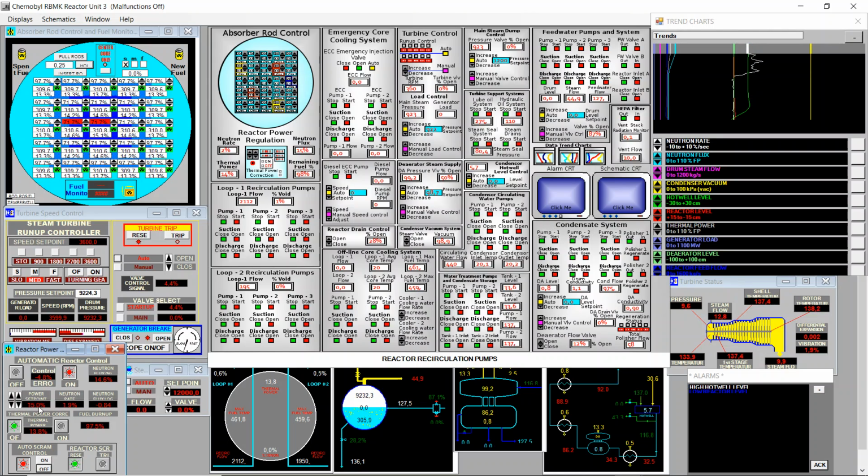Okay, I went beyond by 0.5%, but I just went back very quickly, so it's fine. We see the pressure building up, 9,500 already. And actually the normal procedure is to keep the reactor at 10% during this procedure, during this transition. I just did this to speed up the process a bit, but you are supposed to increase from 10 to 15% after synchronizing the turbine.